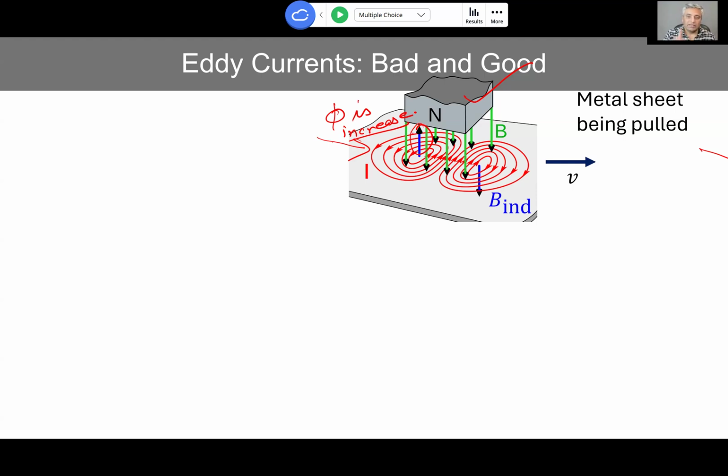Okay. So that means if induced field is up, if you were to point your thumb up and curl your fingers, your fingers curl that way. So that way we know this is circulating that way. So now this current circulating here. Okay. So this current circulating means the electrons are moving there. So they feel resistance. There may not be very large resistance, but any metal has some resistance. Okay. So it experiences that resistance, meaning the current that develops eventually dies down because of the resistance. So when it dies down, that means that energy gets converted into heat. Okay. So this eddy current generates heat.